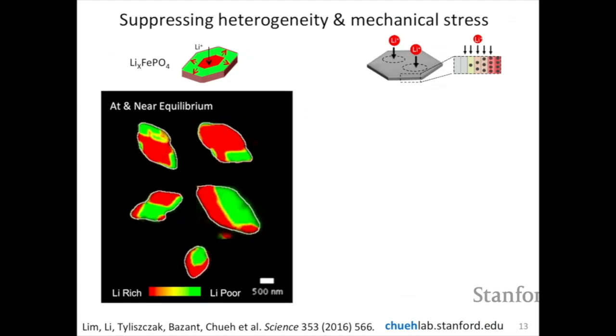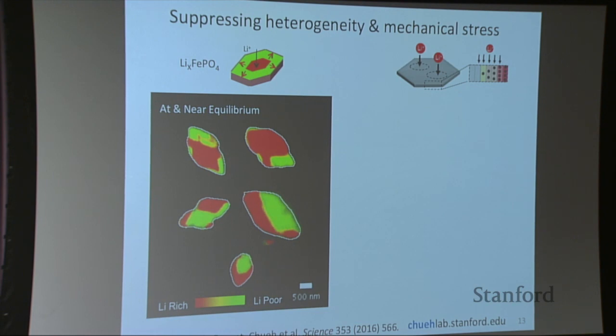So now I'm going to turn the material from the layered oxide, so that's the analog of lithium cobalt oxide, to another related chemistry, lithium iron phosphate. This is commonly found in your power electronics tools. If you have a battery-powered drill or a vacuum, very likely you have lithium iron phosphate. This material has a very specific behavior, which is it either likes to be lithium-rich or lithium-poor. So it doesn't like to be in between. This is known in material science as phase separation. Okay, so it's either full of lithium or empty of lithium and nothing in between.